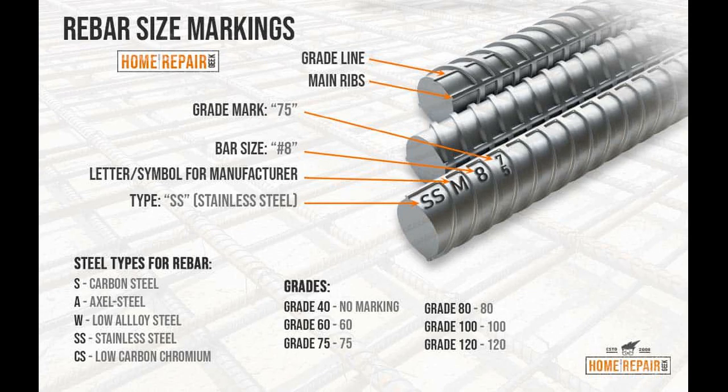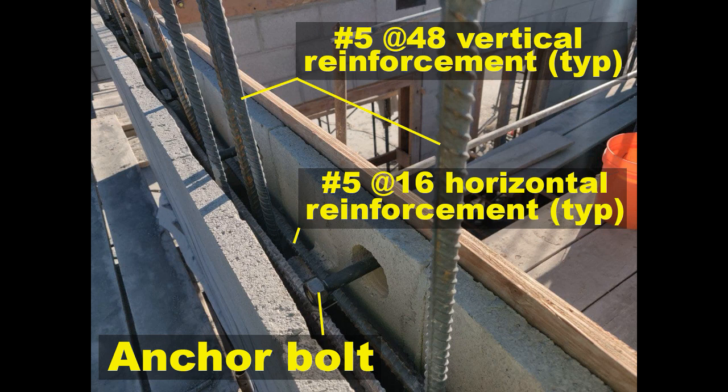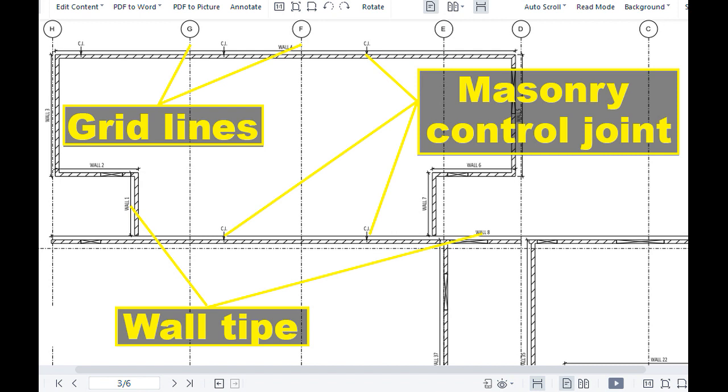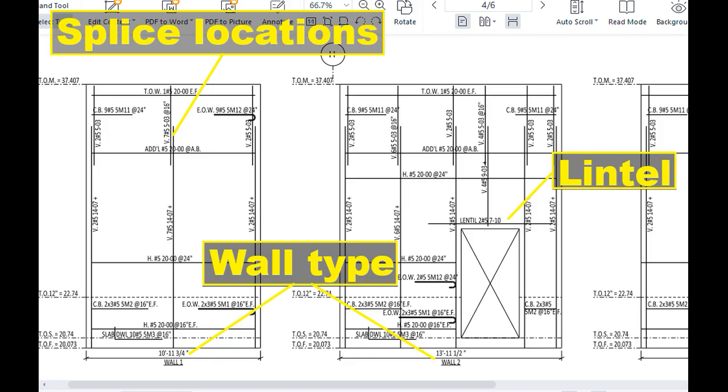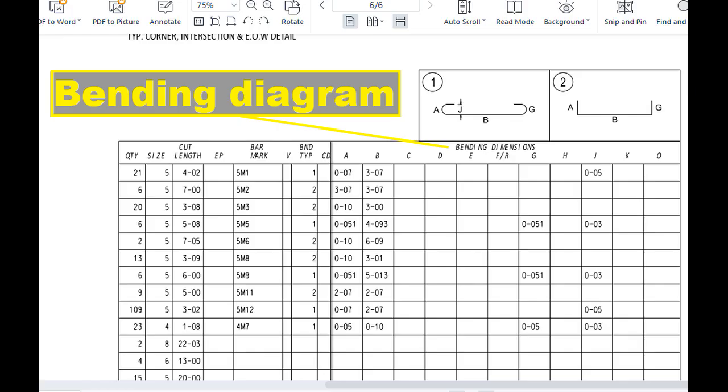Reinforcing steel bars. Reinforcing steel bars and rods shall conform to ASTM A615M or A996M, grade 60 typically, or as shown in the drawings. Bar reinforcement installation. Submit detailed shop drawings showing bar splice locations and reinforcement details compliant with Seismic Design Category D requirements. Identify bent bars on a bending diagram and reference and locate such bars on the drawings. Show wall dimensions, bar clearances, and wall openings.